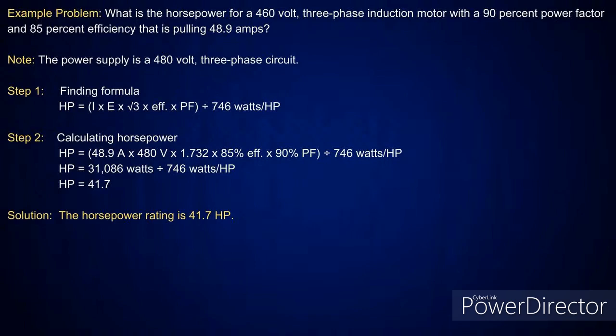And this is a rule of thumb. The way the guys out in the field a long time ago used to do this all the time. Anybody that listened to the podcast, we might get him to do it again. Dad did it on the motors, talking about the rule of thumb, how they would size the horsepower rating, and then look at the overcurrent protection device. He would tell you a rule of thumb, you take it at 300%, 200%. He went through all of that and showed you, and it was based on the frame type of the motor, which is the reason they did it that way.